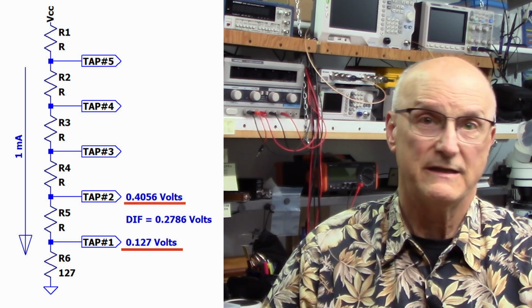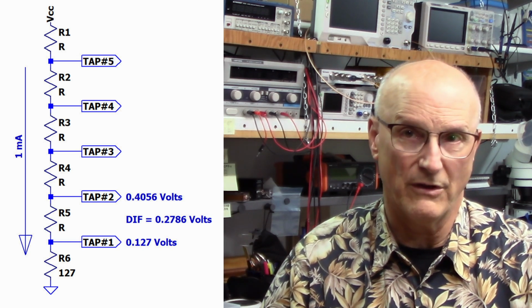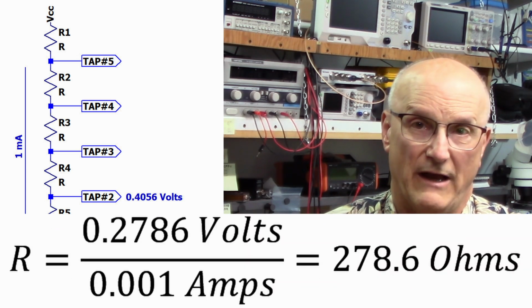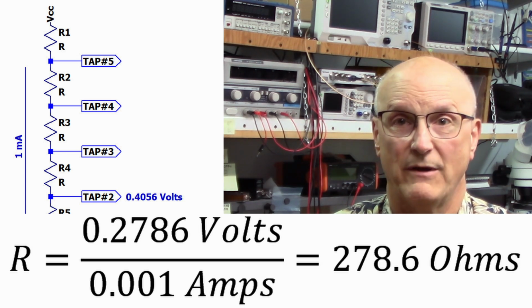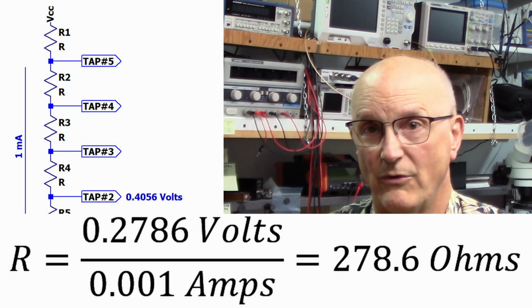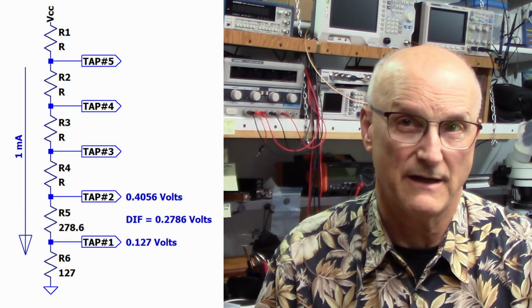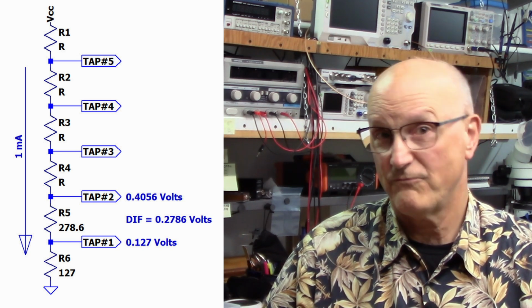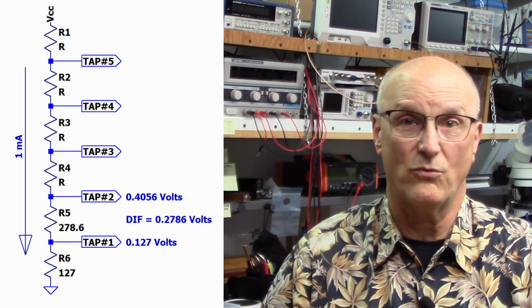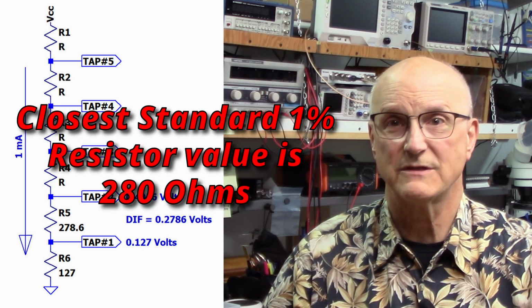Now this is dropped across a resistor that has 1 milliamp flowing through it. So we have 0.2786 volts divided by the 1 milliamp, or 278.6 ohms. Again, not exactly a standard resistor value. So we go out and we look to find the closest standard 1% resistor value, which is 280 ohms.